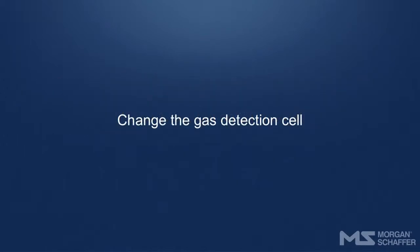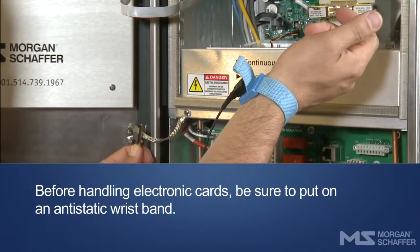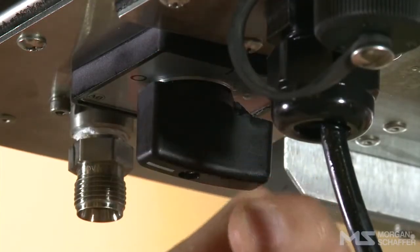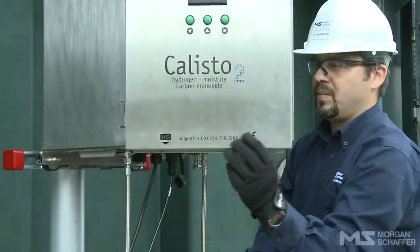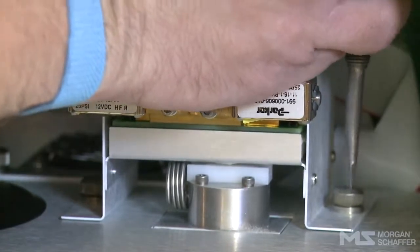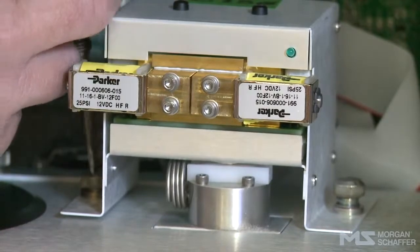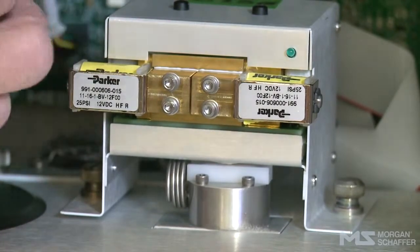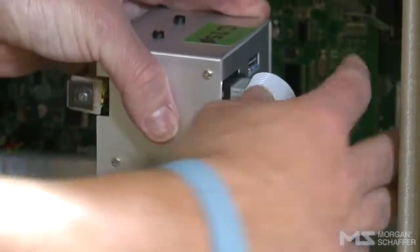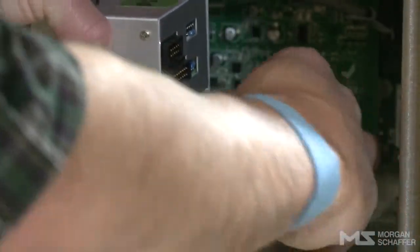Change the gas detection cell. Before handling electronic cards, be sure to put on an anti-static wristband. Turn off the Calisto and close its circuit breaker. Open the Calisto's door. Loosen the 2 captive screws on both sides of the cell. Gently lift the cell, keeping it horizontal. Unplug the 2 connectors of the flat cable behind the cell.